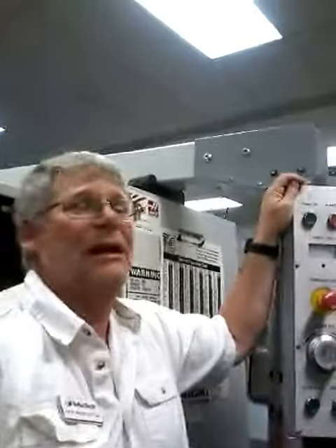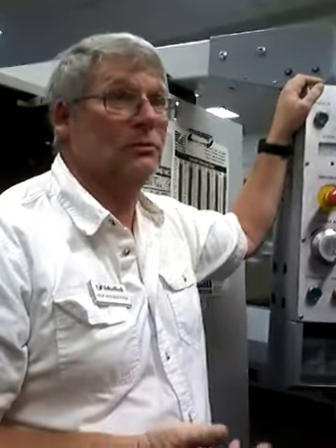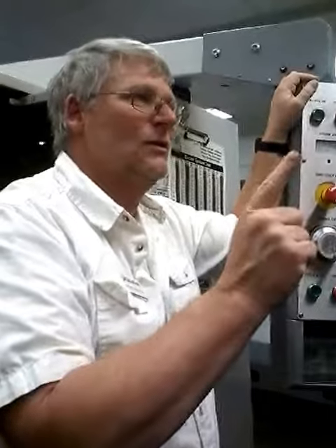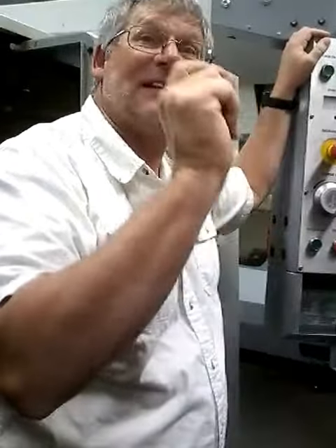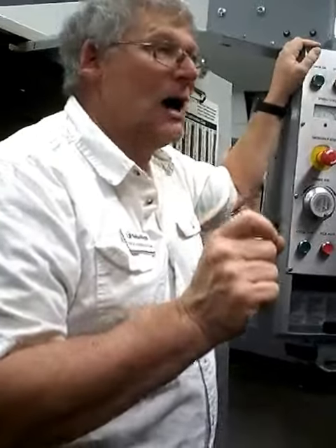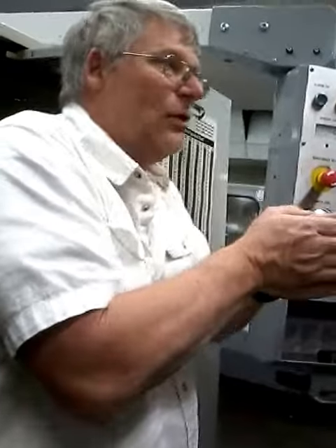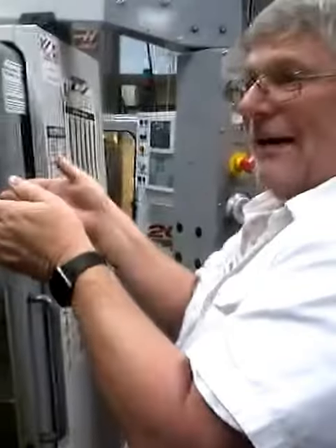So I don't have to remember it, write it down, type it out, risk transposing numbers and all that other stuff. I can just hit part 0 set, it takes the value that I need and puts it where I need it. That's pretty simple, right? But what's the problem? The radius of the edge finder. I'm 100 thousandths off in a specific direction. I need to be 100 thousandths positive from where I'm at, correct?